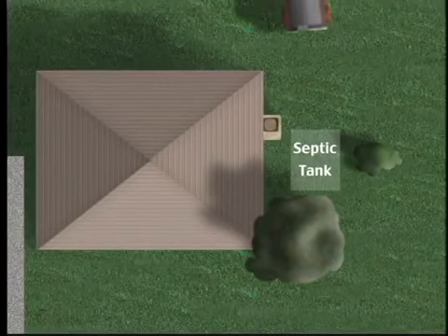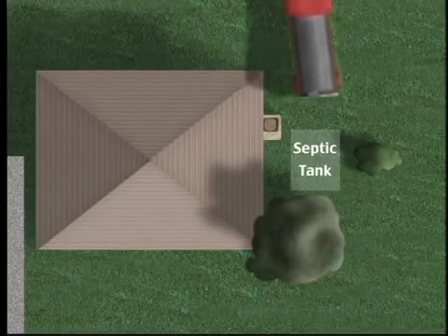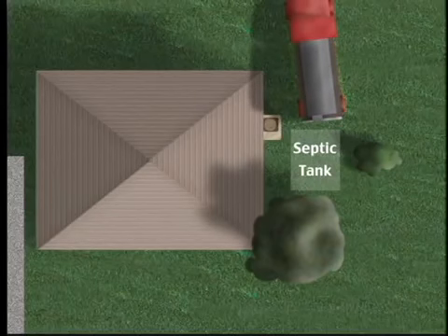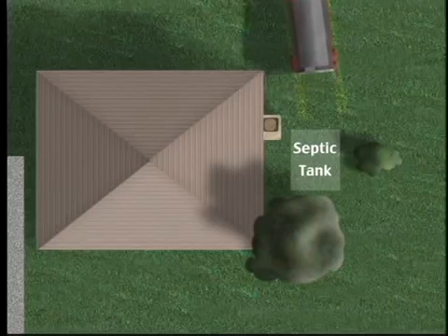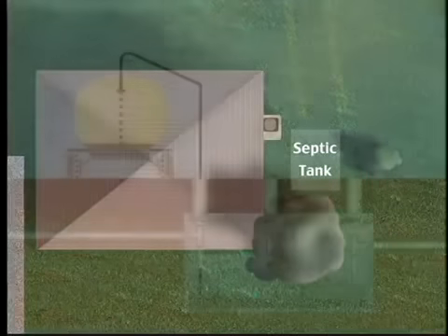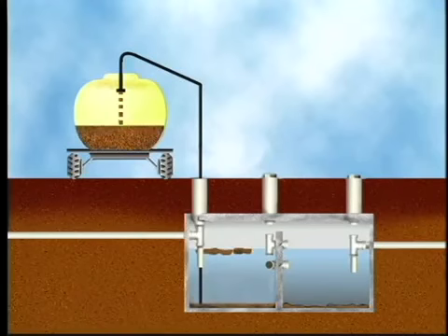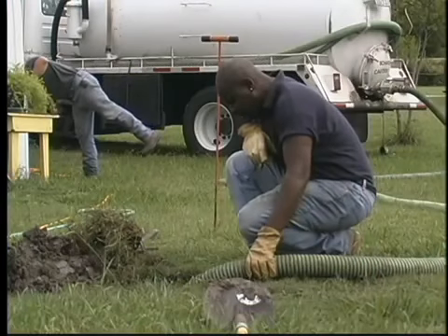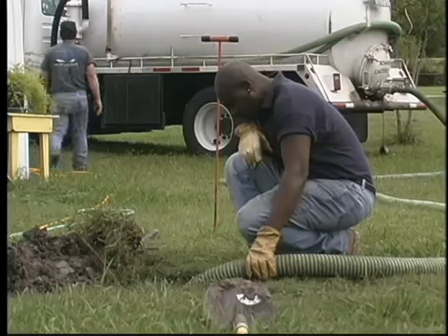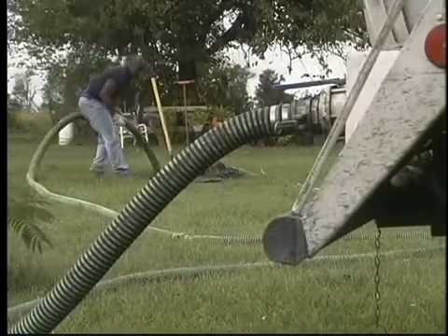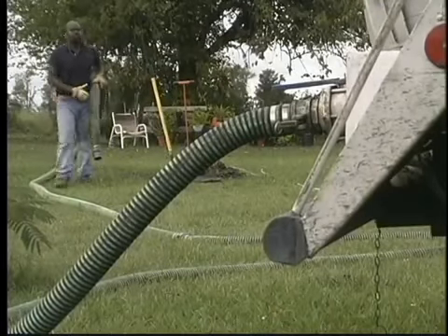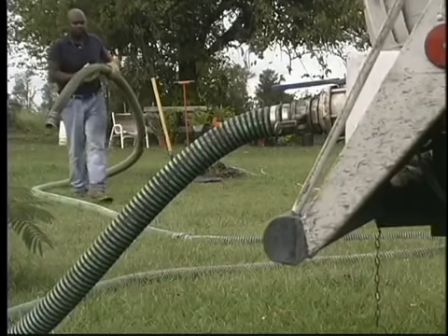Though a treatment system must be a minimum of 5 feet from the building, it is usually placed further away to allow better access for operation and maintenance. Periodically, you will need to have solids pumped from the treatment tank. This is accomplished by a vacuum truck with a hose that extends down into the treatment tanks. Pre-planning on how this truck will be able to get to the tanks will assist further maintenance.